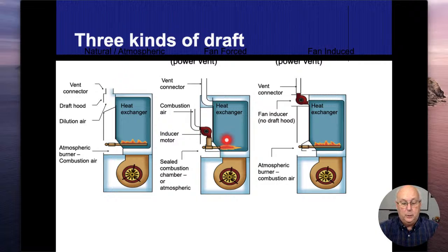All right. The reason we don't do this anymore is when the furnace is starting up and I have a fire going inside, if that is pressurized on the inside, and if there's a hole anywhere on the inside, then I'm going to end up pushing those combustion gases or the after-fire gases or the carbon monoxide into my circulation air.